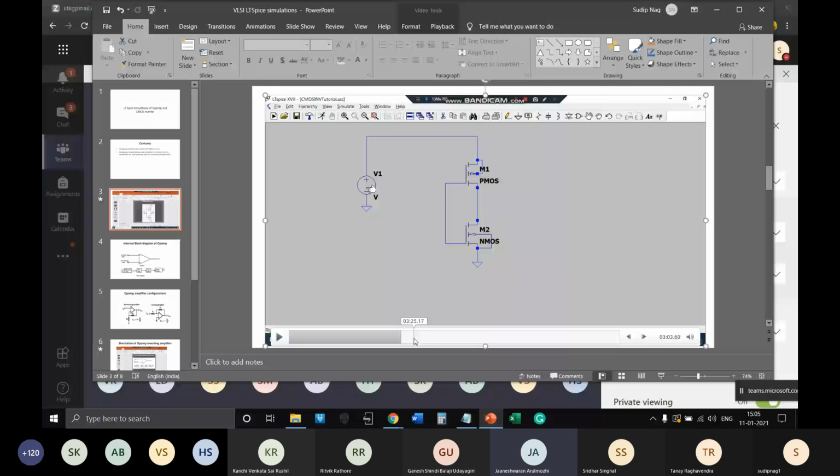Yes, sir. There is a body substrate as well, right? The substrate is the middle terminal, which is shown by this arrowhead, either going in or out based on NMOS or PMOS. But in standard MOSFETs, source and drain are interchangeable because it's a symmetric device. If you consider 4-terminal MOSFETs, in that case, the substrate is closer to the source terminal. If you look at the cross section of a 4-terminal MOSFET, the substrate connection is done through doping of one of the semiconductor layers next to the source terminal, and you have to short them.